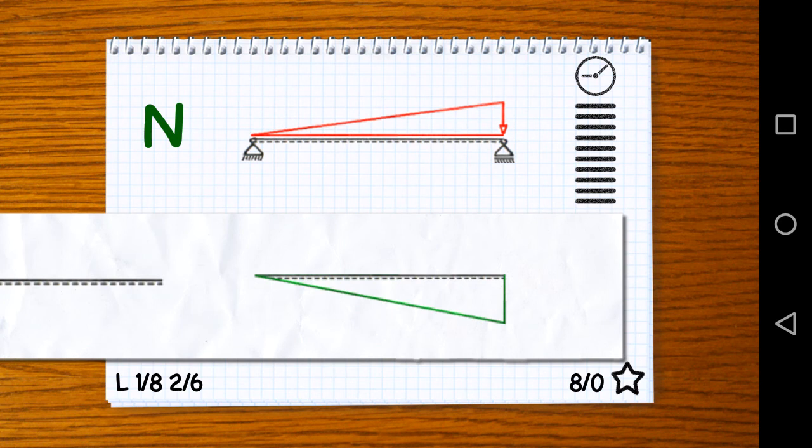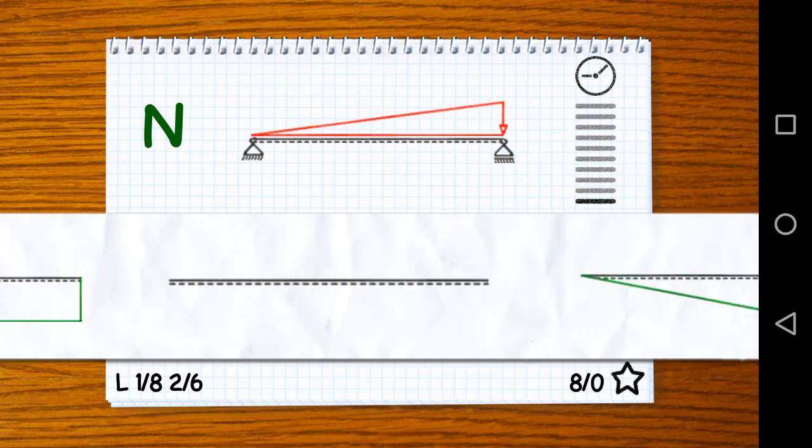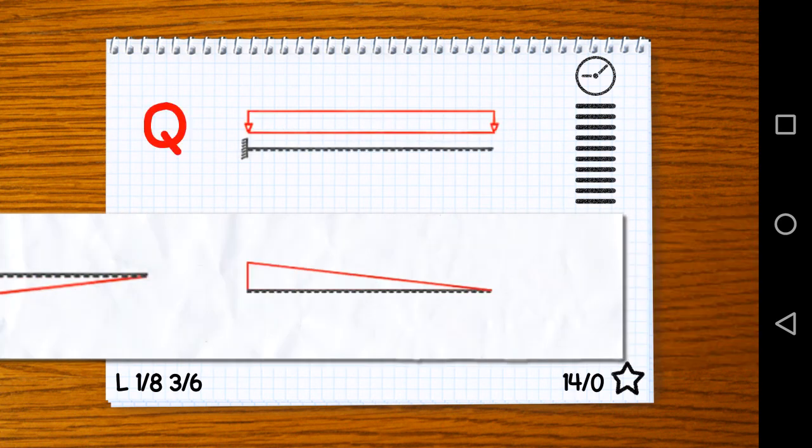Now, what happens here? We have a vertical loading. It's a linear loading, but it doesn't matter. It's a vertical loading, so our supports are going to have reaction forces upwards. But if we sum the forces in the horizontal direction, we see that there's no loading in the horizontal direction. The right support, the roller support, can't take any loads in the horizontal direction anyway. The left support, the pin support, can take forces in the horizontal direction, but it would be the only horizontal force here. So when we sum the forces in the horizontal direction, that force is going to be zero.